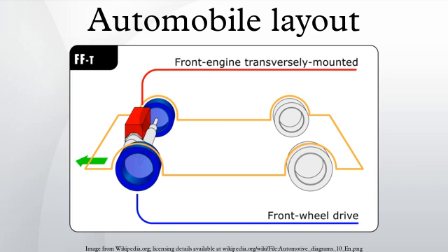It makes heavier use of the front tires, causing more wear in the front than in a rear-wheel drive layout. Under extreme braking, the already front-heavy layout further reduces traction to the rear wheels. This results in disproportionate gripping forces focused at the front while the rear does not have enough weight to effectively use its brakes. Because the rear tire's capabilities in braking are not very high, a significant number of cheaper front-drive vehicles use drum brakes in the rear even today. The steering feel is more numbed than a rear-wheel drive car. This is due to the extra weight of drive shafts and CV joint components that increase unsprung weight.